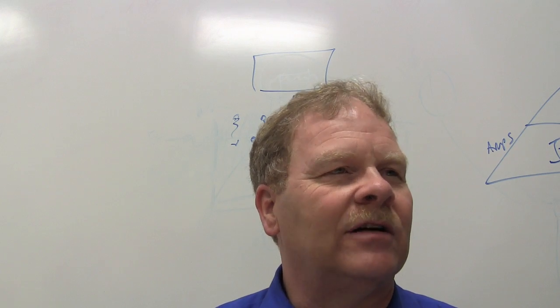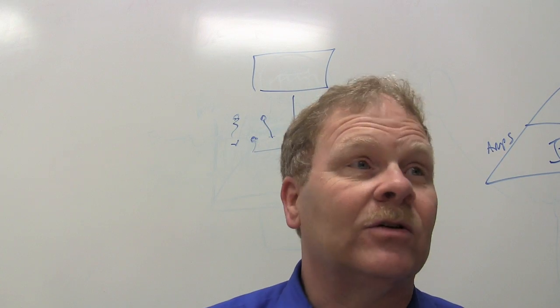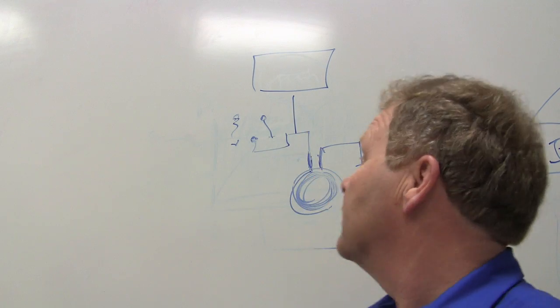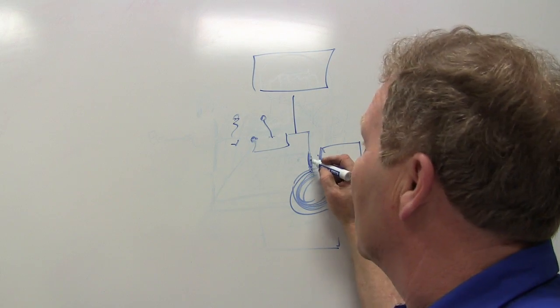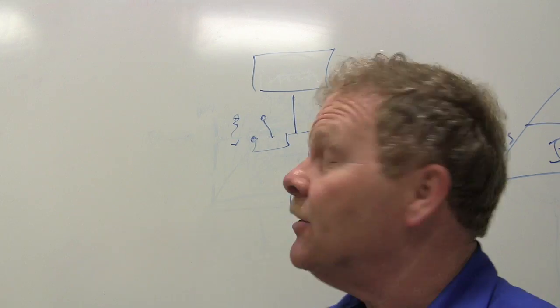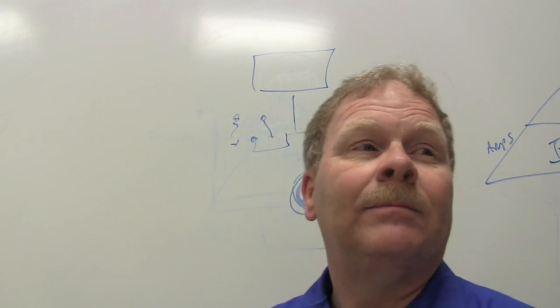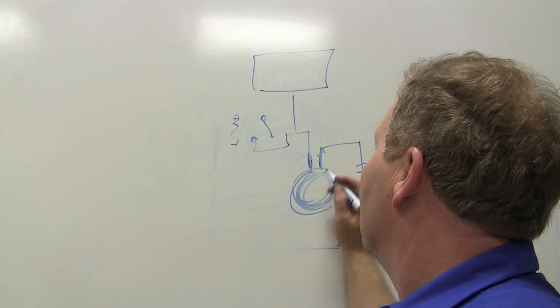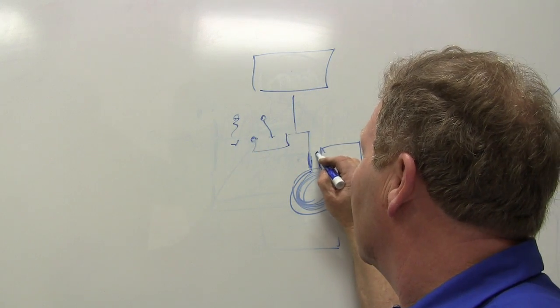What does that remind you of? An ignition coil. What does an ignition coil do? It makes a dadgum spark. It will knock you on your fanny. This right here will send a 400 volt spike screaming right into the heart of that PCM, unless there is a diode in there.